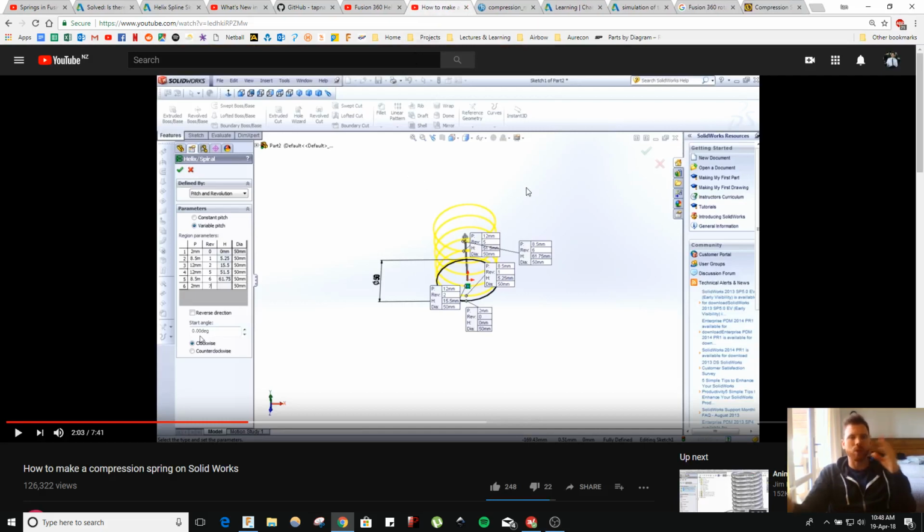This is kind of the gold standard in my view. Sorry, I don't really want to close that tab. This is the tool that's in SolidWorks at the moment, and it's pretty user friendly. There's still some features that I would think are missing from it, but it's definitely a step up from what's currently in Fusion. Instead of doing just one or two coils and then joining them together, you can have a variable pitch coil, which you can have as many turns or as few turns as you want, with fractional turns.